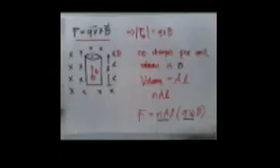The force is always perpendicular to both the conductor and the field, with the direction determined by the same right-hand rule we used for moving positive charge. Hence, this force can be expressed as a vector product, just like the force on a single moving charge. So we represent the segment of the wire as a vector L, along the wire with the direction of the current. Then the force F on this segment is equal to the current times the cross product of length and the magnetic field.